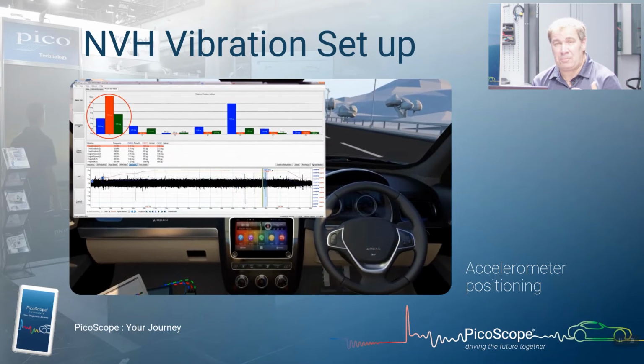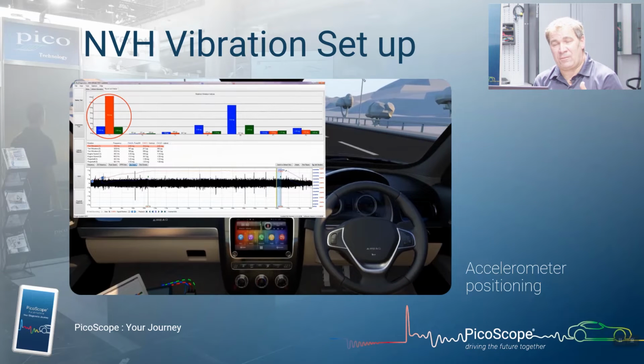Those 3 colours respond to the 3 axes of the accelerometer. So we've got our forward and backward, our side to side, and our up and down. And the red one being the up and down, I think, isn't it? That's correct. Yeah, that's right. And that's important because in that first measurement, we know what we're trying to look for is most likely caused by an up and down movement. And that helps us when we go on to the next part of the test, where we're going to introduce another measurement at a different point in the vehicle, so we can start to try and narrow down where we feel the issue is.